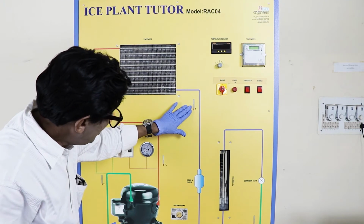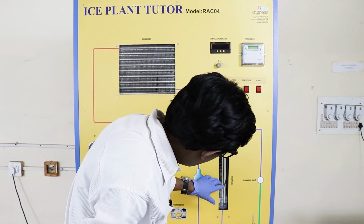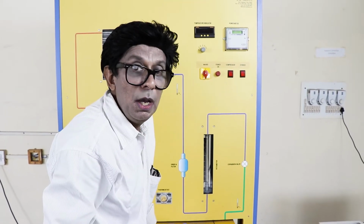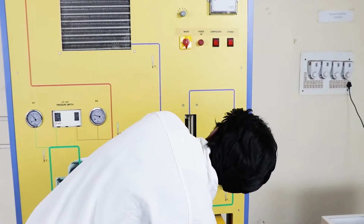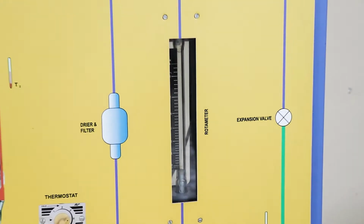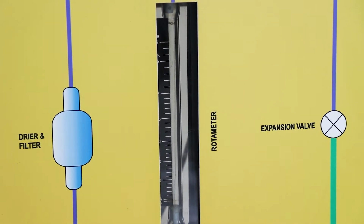The temperature is T3 here, and then this is the rotameter, which gives us the value of the flow rate of the refrigerant through the whole system. This reads in liters per hour, but usually we are using SI units, so this liters per hour will be converted into kg per second.